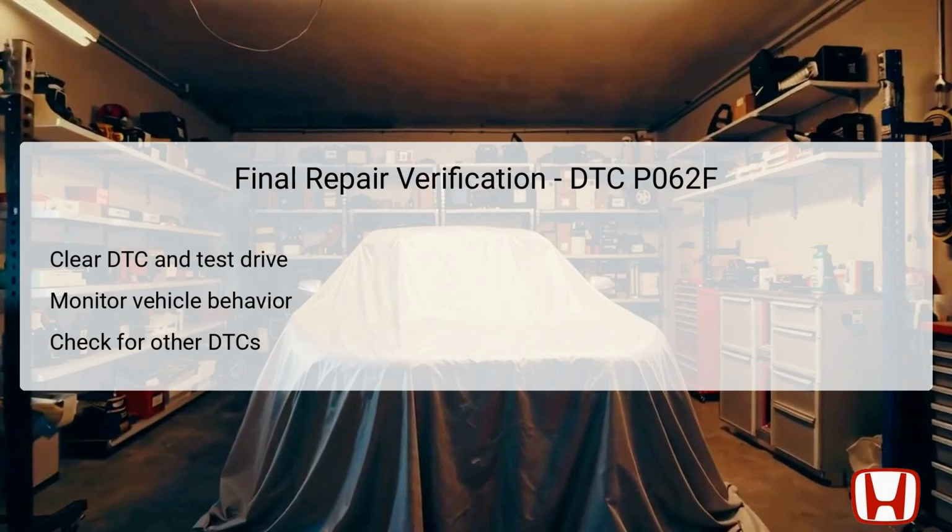After the test drive, it is important to check for any new pending or confirmed DTCs with the HDS. This step ensures that no other underlying issues are present that could lead to erroneous vehicle operation, providing a clean slate to confirm repair success. Comprehensive testing will validate whether the issue has been resolved or if additional actions are necessary.